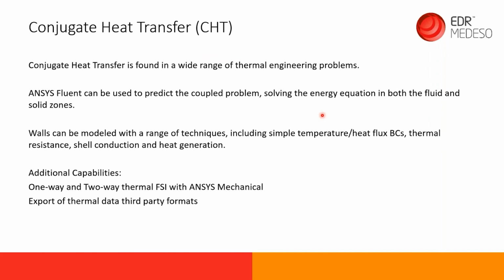Just a quick summary then. CHT is found in a wide range of thermal engineering problems. We can use Ansys Fluent, Ansys CFD, to predict the coupled problem, the flow field and the solid conduction. We have to consider the methods of dealing with wall heat transfer, and as you've seen in Ansys Fluent, there are a number of ways of doing that, a number of ways of dealing with those difficult thin surfaces using shell conduction.